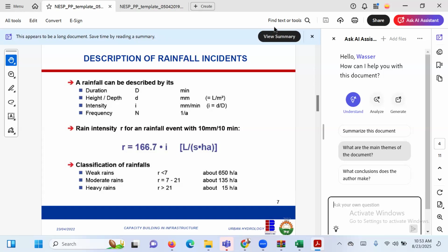What do they mean by 50-year flood? What they are trying to say when they say 25-year flood, 50-year flood, 20-year flood, 5-year flood, 10-year flood, it is the frequency, the probability of that flood occurring. That's what they mean. How do we say it was a 50-year flood? Because the last time that flood happened was in the 1960s. Those who are alive in Bayelsa testified to that. They say the last time we experienced that kind of flooding was like 50 years ago. It means that this kind of rain comes at least once in 50 years.